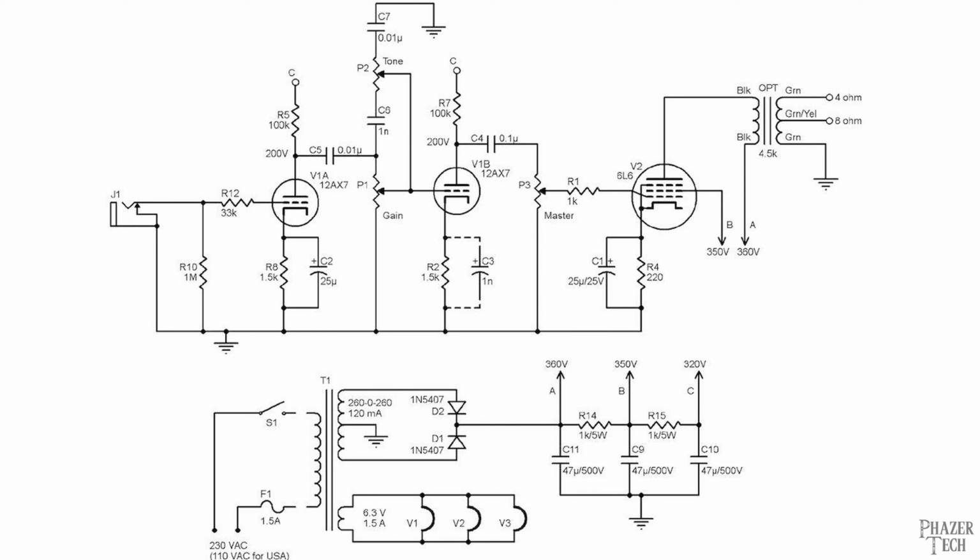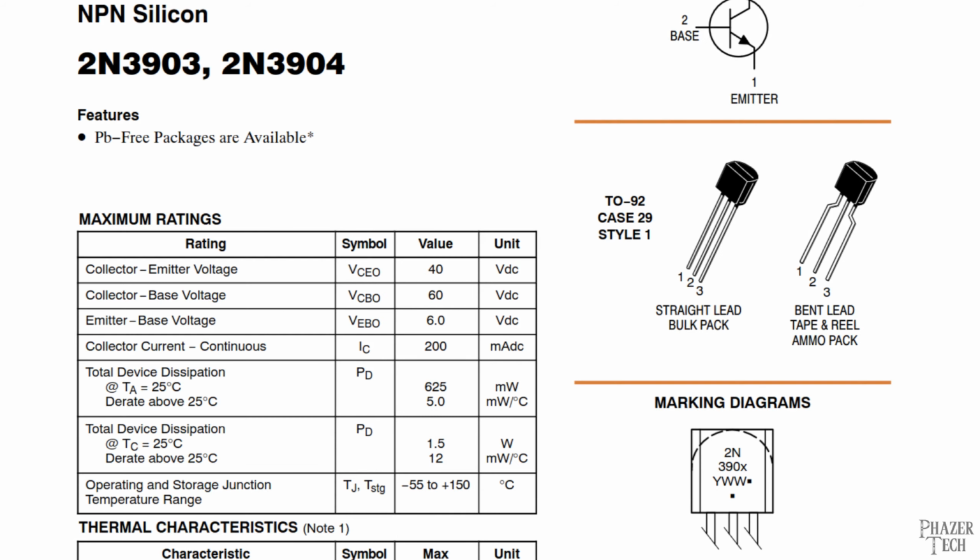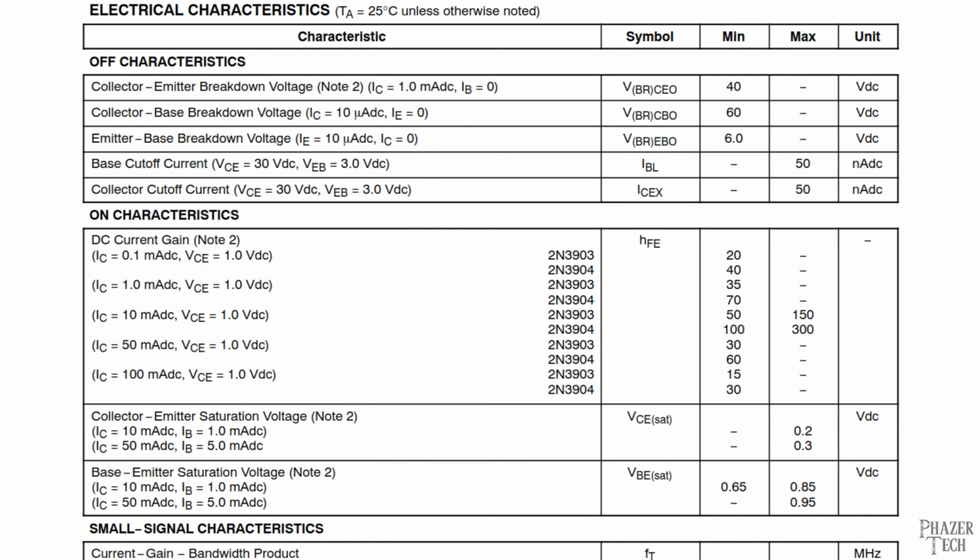If the voltages you measured in a particular spot are drastically different from the calculated values, then you know the issue is in that location. If you're dealing with active components and ICs, then you'll also want to look at their datasheets to determine what sort of voltages you can expect from those components.